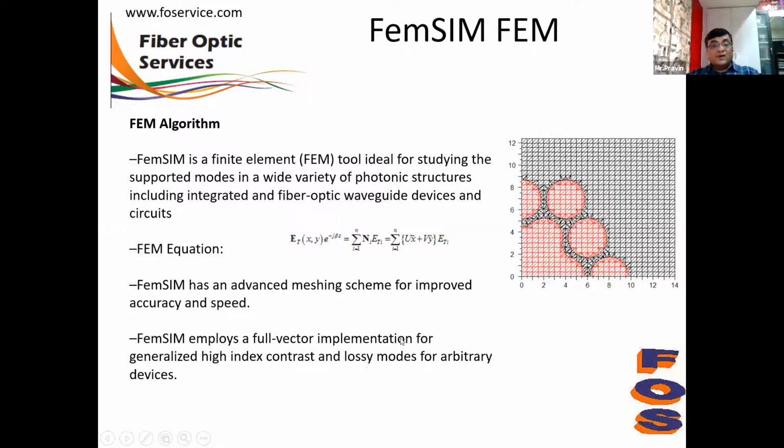FEMSIM employs the full vector implementation for high index contrast materials and structures and low index contrast structures, whereas particularly when you are using the BPM based tool, they are more for the low index contrast material.